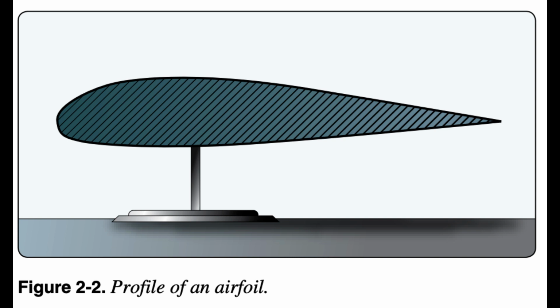The goal is for the blade to defy gravity and stay exactly where it is when we remove the stand. If we do nothing before removing the stand, the blade will simply fall to the ground. Can we exert a force, a push or pull, opposite gravity that equals the 100 pounds of weight of the blade? Yes, for example, electromagnetic force could be used. In helicopters, however, we use aerodynamic force to oppose weight and to maneuver.